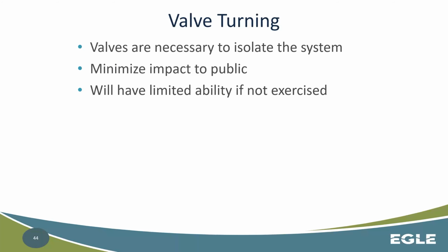Valves are necessary to isolate portions of the system when we have to work on them or do other maintenance to those portions. Valves help minimize the impact on the public if we have an emergency or some other thing occurring. And then they'll have limited ability if not exercised. Meaning that if you don't exercise a valve over time, many things can happen.